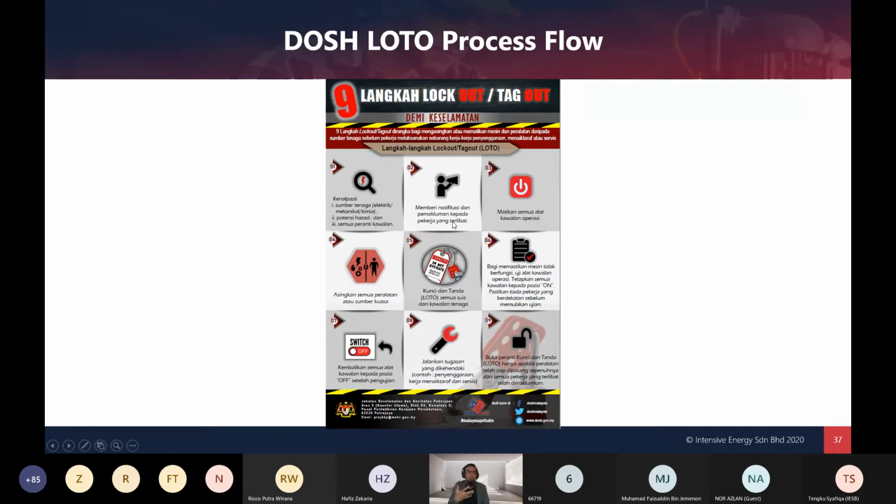In our organisation, sometimes we don't inform using a hailer or paging. We use PTW as information. PTW is also a communication tool. Switch off, isolate, install LOTO, set all function controls to on during testing, return all devices to off, do maintenance, remove LOTO.